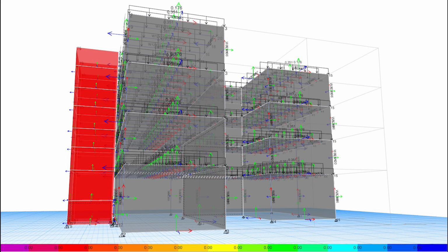In this video, I'll be using a 4-story building with an external elevator core. The lateral force resisting system consists of intersecting moment frames. The elevator core is structurally isolated. The building will have a maximum beam depth not exceeding W18 to allow sufficient clearance for ductwork running beneath the beams. Starting a new model.